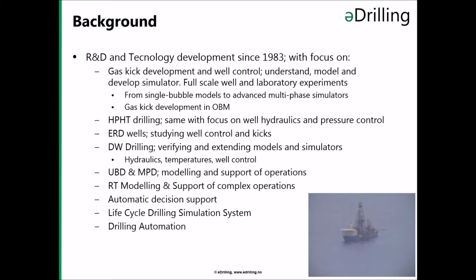After this period, I went over to focus on drilling high pressure, high temperature wells and looking into what specific elements were of specific interest and high focus in these wells. I focused mostly on hydraulics and pressure control. For a period, I also studied well control and kick development in extended reach wells.